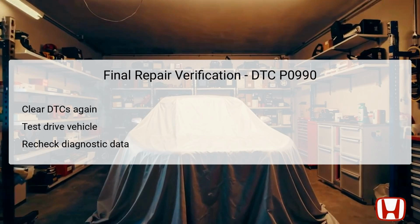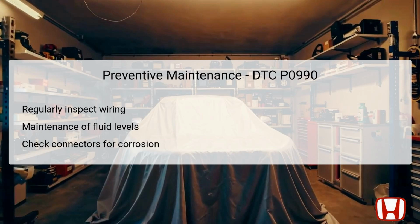A successful verification indicates that the troubleshooting and repair process has been effective and that the vehicle is ready for normal operation. Preventive maintenance plays a vital role in ensuring that issues like DTC P0990 do not arise unexpectedly. A periodic inspection of the wiring associated with the transmission fluid pressure switch is recommended to catch any signs of wear or damage early. It is equally important to maintain proper transmission fluid levels, as low fluid can lead to pressure discrepancies that could affect performance.